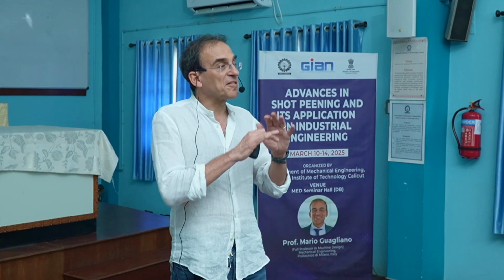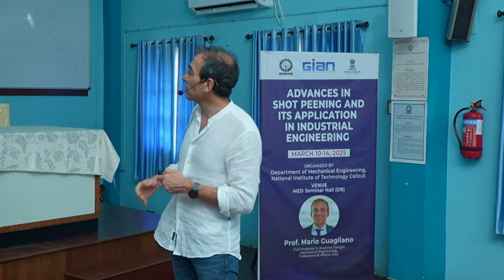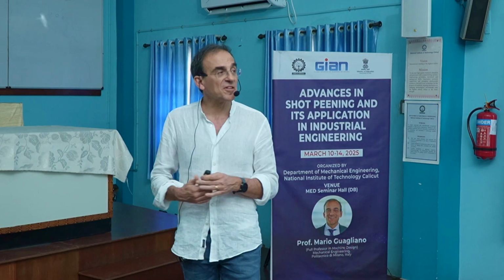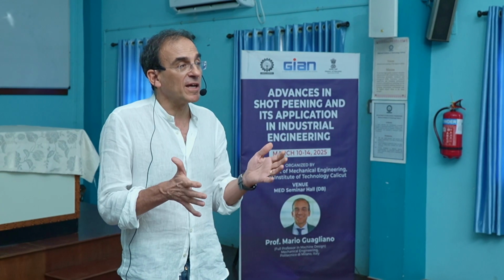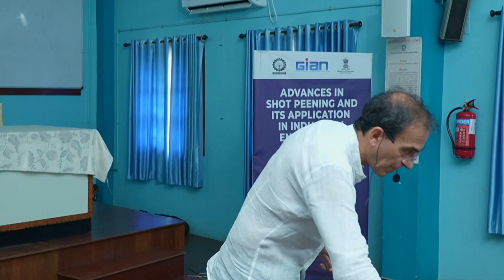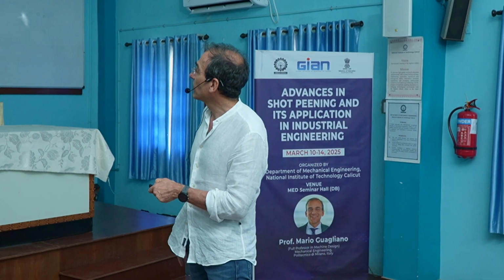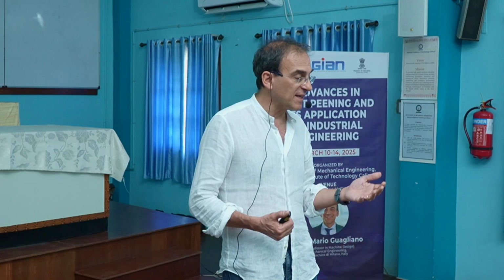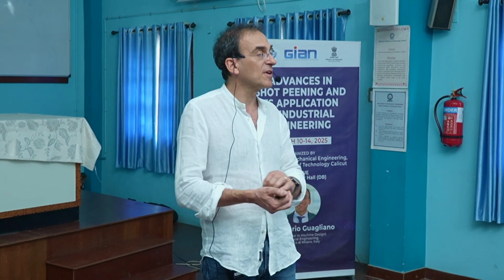Let's see and discuss some practical problems related to the application of XRD. Indeed, the first is the choice of the right radiation. Not all the materials react the same way with respect to the X-rays that we are using. If we are using a chromium anode for generating X-rays, a chromium radiation, this will be good for some materials because we'll be able to cause diffraction for aluminum alloys, for instance, for many steels. Okay, but it will not be good for Inconel. Why? Because in this case we need a copper radiation.